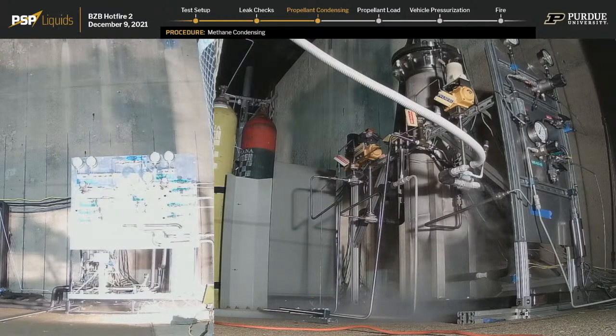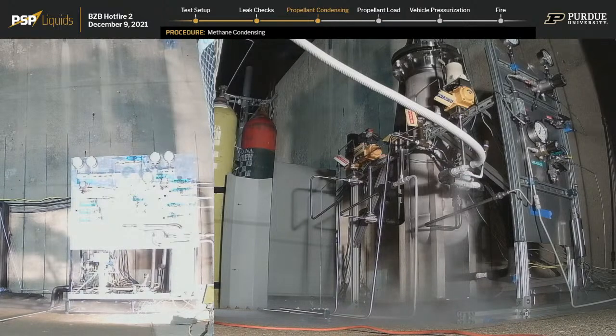We are letting the cold flow now. As you can see, another thing we have on this system in particular is standoffs, and long ones at that. Can you go over what the point of standoffs are in the system? Yeah, so thermal standoffs are really important when you're working with a cryogenic system to make sure that when you're reading something like a temperature or a pressure, you're reading the temperature where you actually want to, and that you're not just reading the temperature in metal, I believe. Yeah. And in valves, if the valves themselves are way too close to, or the actuators are too close to the valves, they'll actually freeze, and that is definitely something we want to avoid in this system.